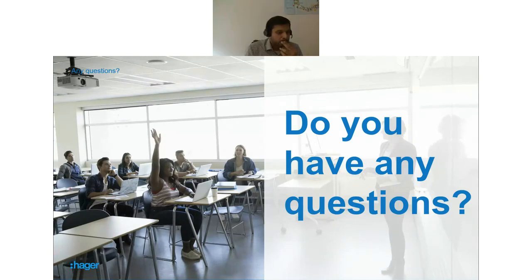Now let's check another question. If I have 60 meters from the distribution board to the final socket, does this work? Okay, I understand. If I understand well, you mean you have installed the SPD at the distribution board, and then your computer or end device is 60 meters away from this distribution board. If my understanding is right, then your computer is not protected. You need to install another SPD nearby.